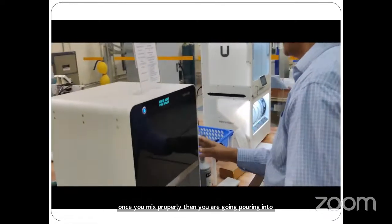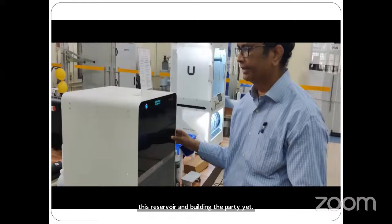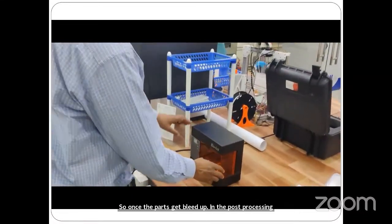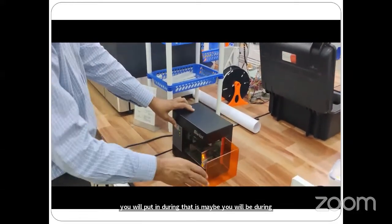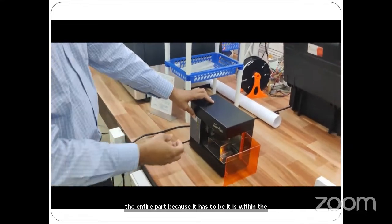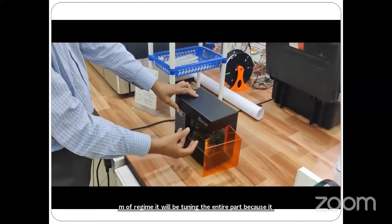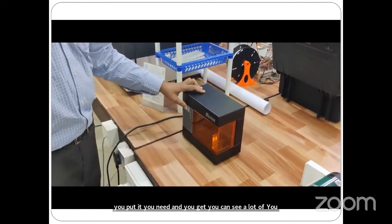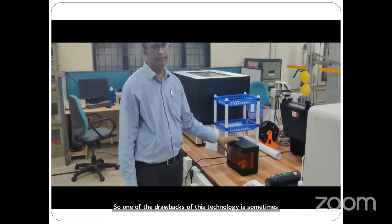Once the part gets built up, in post-processing you put it in this curing unit. That is where you cure the entire part, because it will be in resin form, some liquid type, so you have to dry it. For that you put it in curing, and you can see a lot of UV light coming here and curing it. One drawback of this technology is that sometimes the curing time will be more than your actual building time.